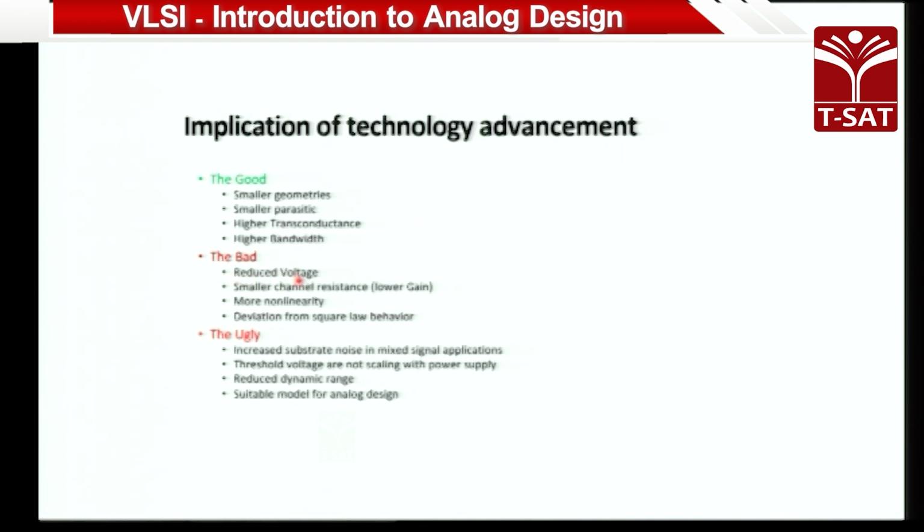Once we go from one technology to another, the power supply voltage is scaling down. But the threshold voltage of the device, after which the device works intentionally, is not scaling down. So you end up having more challenges day by day as we go from one technology to another. That's why you are seeing more failures originating from analog, and that's the reason we need more experts who can deal with all those additional factors going forward.